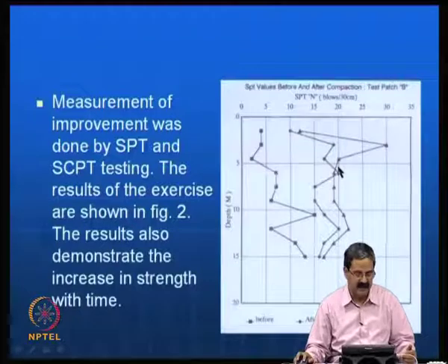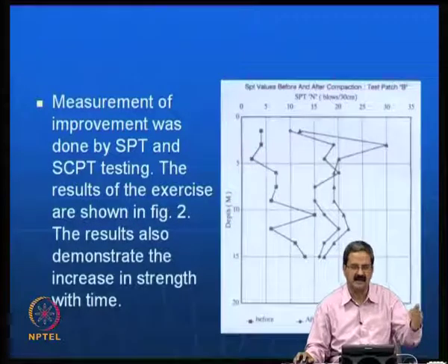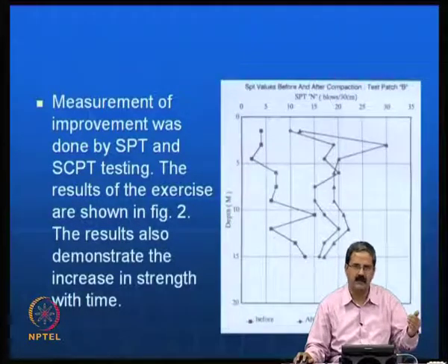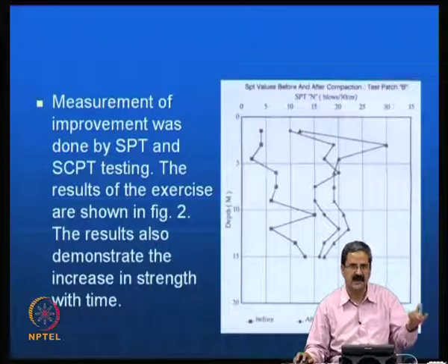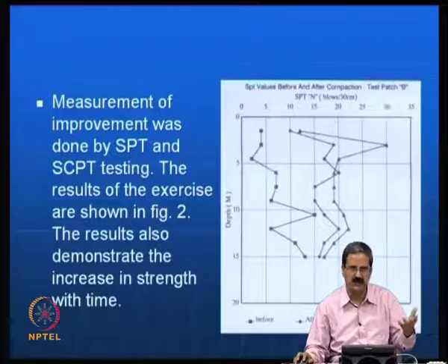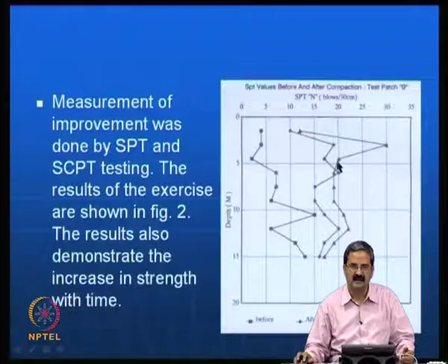What it means is that time dependent behavior is there. If you allow things to happen, for example, consolidation is a time dependent phenomenon in clays, and even in sands, because of the pore pressure dissipation, in about 15 days to 1 month there was an increase in strength which was observed, which is good.